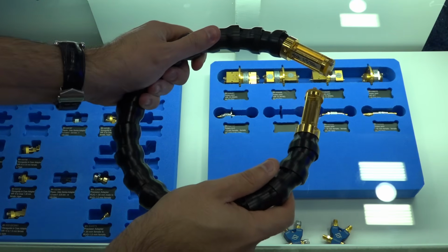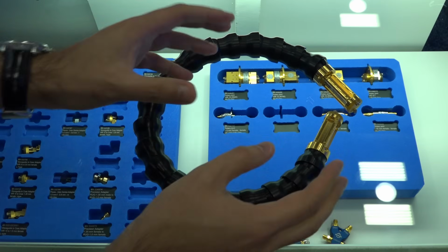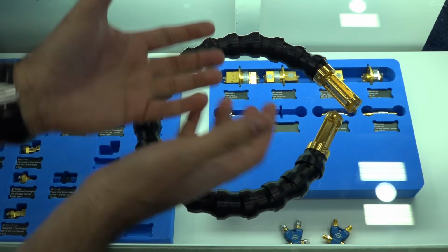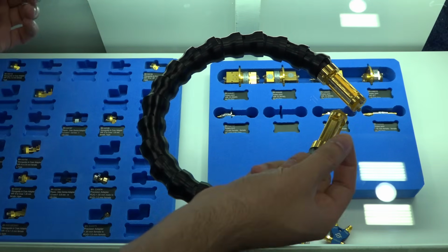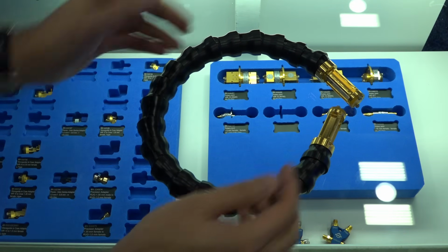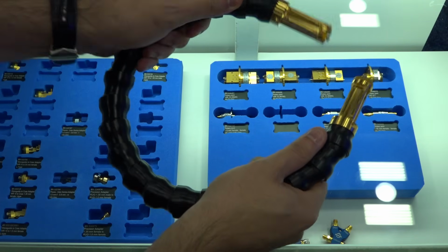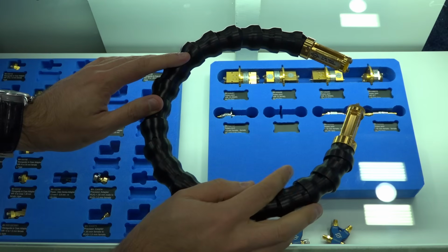Now here we have a really interesting one. The inside of this, there's a dielectric waveguide. The way the fields travel in a dielectric waveguide is they can actually extend beyond the boundary of the dielectric. So you have to have it float inside of the casing material, and that's why this structure is there. It's all custom made in order to do this. So as you twist it and rotate it around, it maintains that dielectric waveguide location inside of this entire cable.